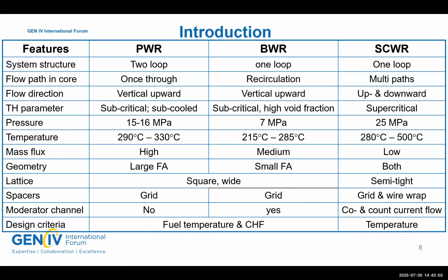For the BWR, yes, we have some moderator channels, but for the SCWR, because you know the density of the water decreases sharply, it cannot provide enough moderation for the neutrons. So we need the moderator channels. And in the moderator channels in the SCWR, they have counter-current flow in different directions. In the vertical direction, it is downward and upward.